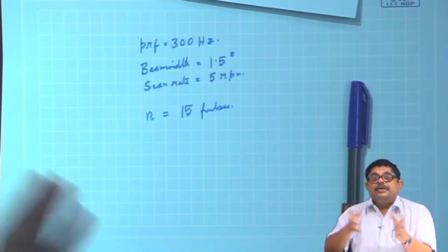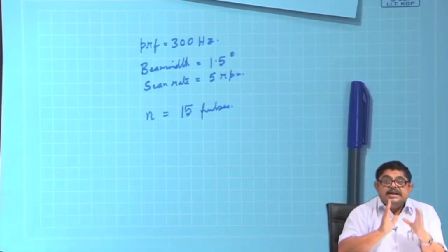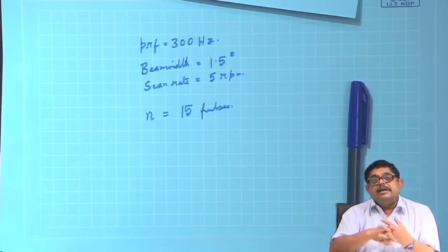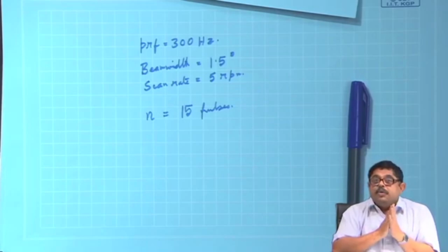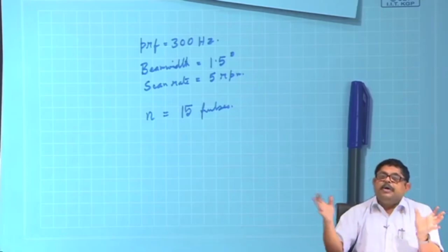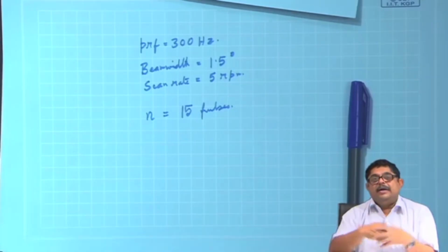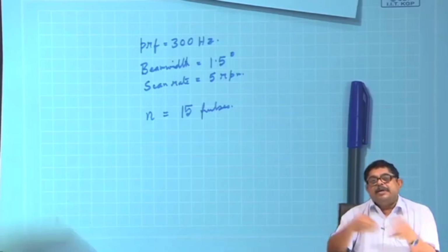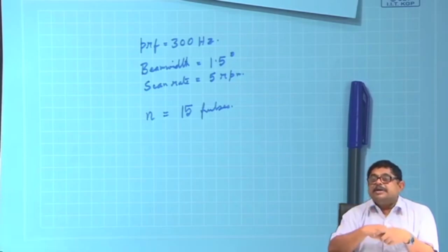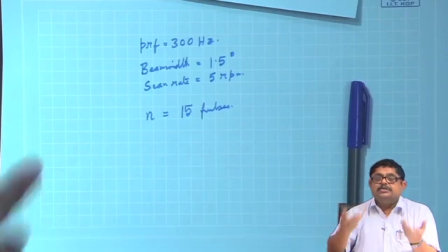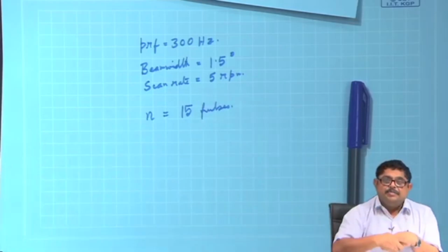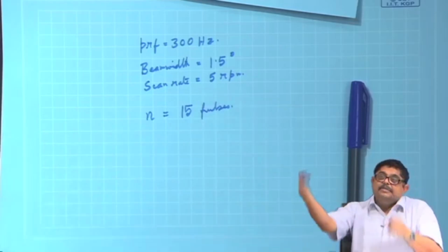The answer is no, because the signal that I am sending is a deterministic signal, and noise is a random signal. So, if you add a noise corrupted signal, the signal power will always add up, but the noise power will go to its mean. So, if you have zero mean noise, then the more pulses you use for integration, the more your noise will go down, and that is an added advantage of detection.